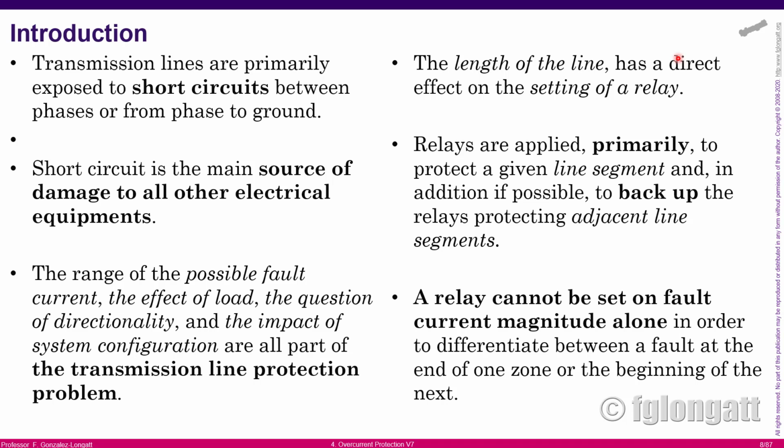However, the power system is subject to faults, especially transmission lines, because they are the longest component in the power system, and because they move through different geographical areas and are exposed to many things, a short circuit can happen. For that reason, the short circuit is probably the most important cause of damage to power system equipment.